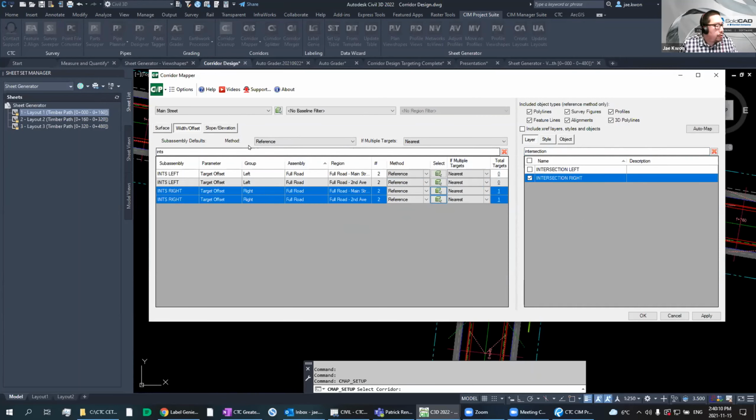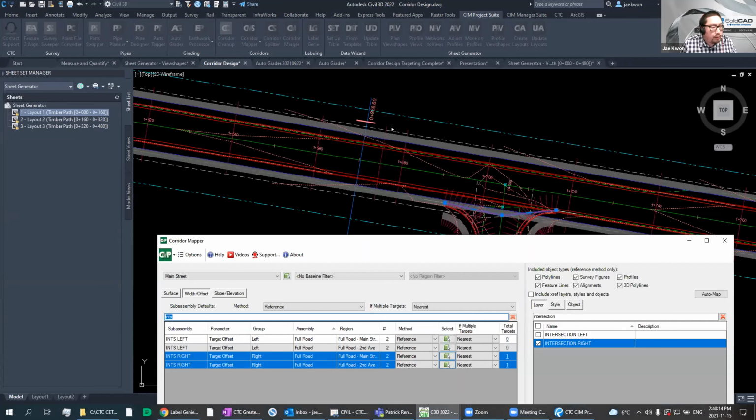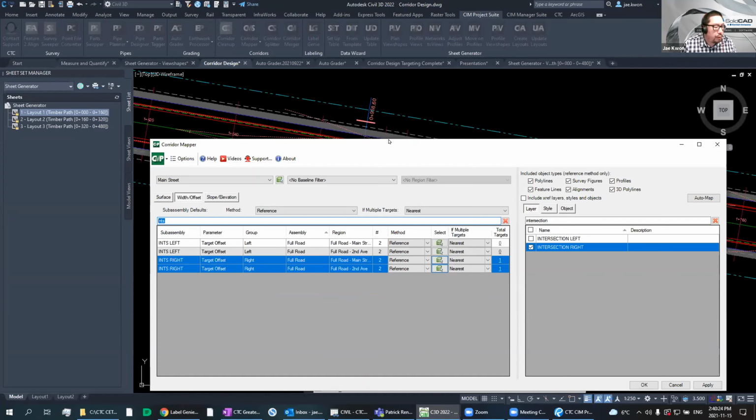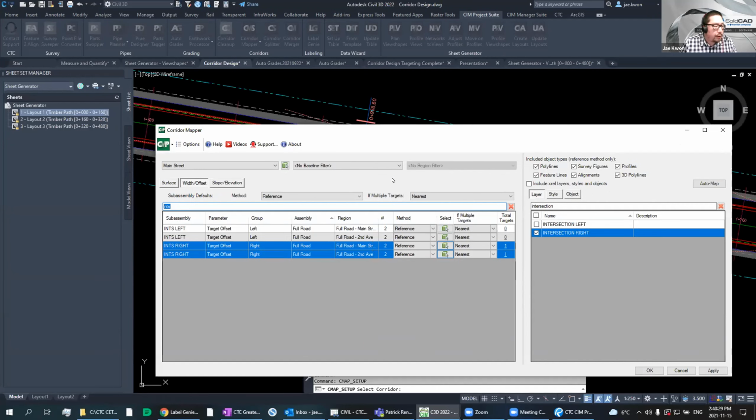And finally, there are driveway cuts. You can see these driveway cuts. There are horizontal target conditions for those. So if those lines exist, just do a mountable curb. Otherwise, do a barrier curb and draw the sidewalk.